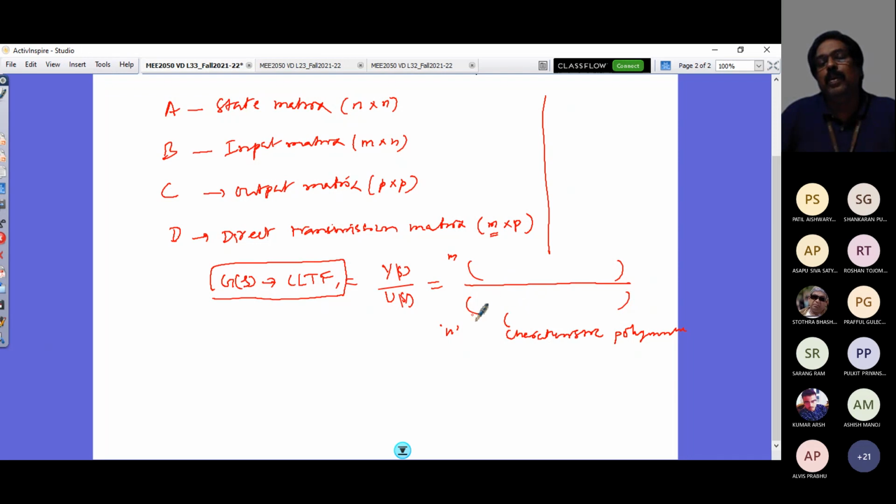And then to find out the roots of this denominator polynomial, you are required to go for the partial fraction technique. And that's going to be sometimes very complex, even to be handled by MATLAB, if there are some parameters that are deciding the characteristic of the system. So in such cases, getting the roots of this characteristic polynomial for an eigenvalue analysis problem can be skipped if you go for a method proposed by Routh's stability criterion, that we will see in a while.